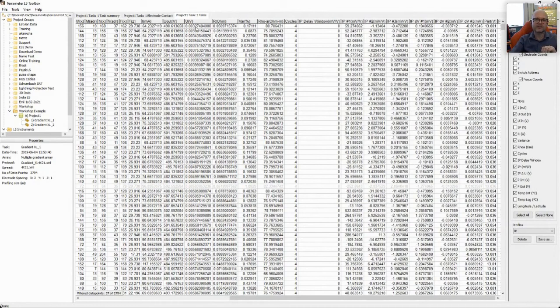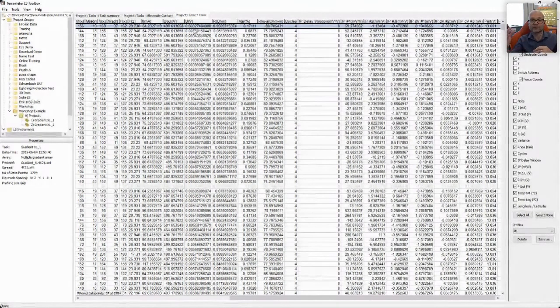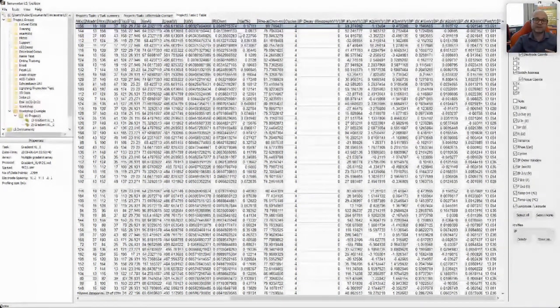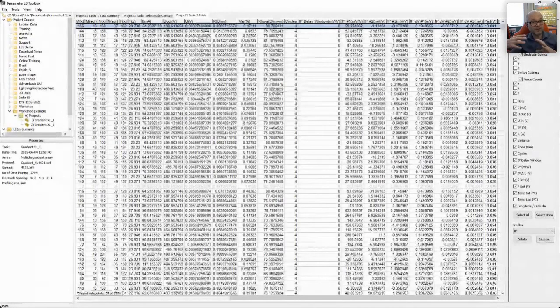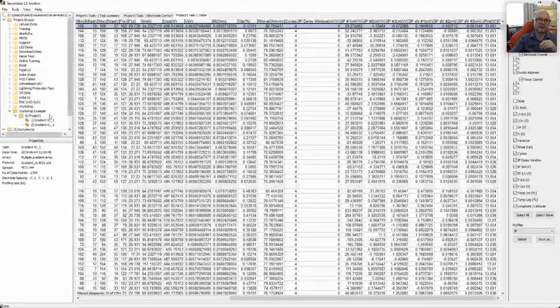And here our smallest measurement is 0.0032, so we're more than double that threshold. I don't actually need to filter anything out here. But if we do have those very small values, the assumption is that they're probably falling into the background noise. If we want to be sure, we can actually look at the full waveform of these measurements.